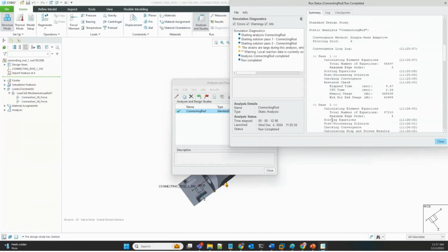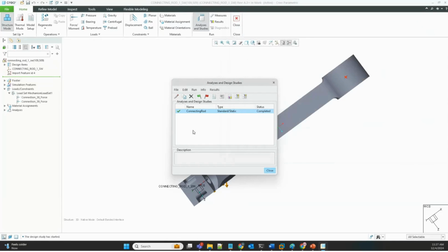And so, again, this is one of the things that makes it easier to use, is the fact that for the same mesh, for the same geometry, for the same analysis, Creo Simulate can run this and iterate 3, 4, 5, 6, 7, 8 times, right? Which saves the user the trouble of having to always refine a mesh, rerun, compare the differences. If there's a big difference, go refine the mesh again and rerun, right? Which is a typical workflow that you would normally do in an FEA analysis study.